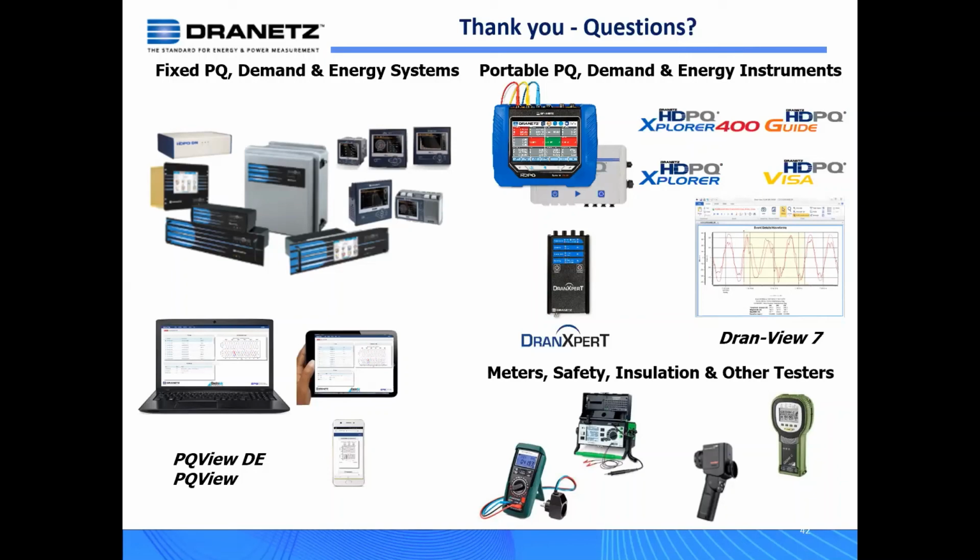The way the instrumentation works these days is that for what we'll call fast changing power quality events, like RMS voltage and current and transients, we're looking at every AC cycle. However, the kW and kVA in most instruments today are measured at 200 millisecond groups, so it's averaged over 200 milliseconds. Very short-term things may not be reflected in your kW or kVA, but longer term beyond that, yes, it's a very good reference to use.